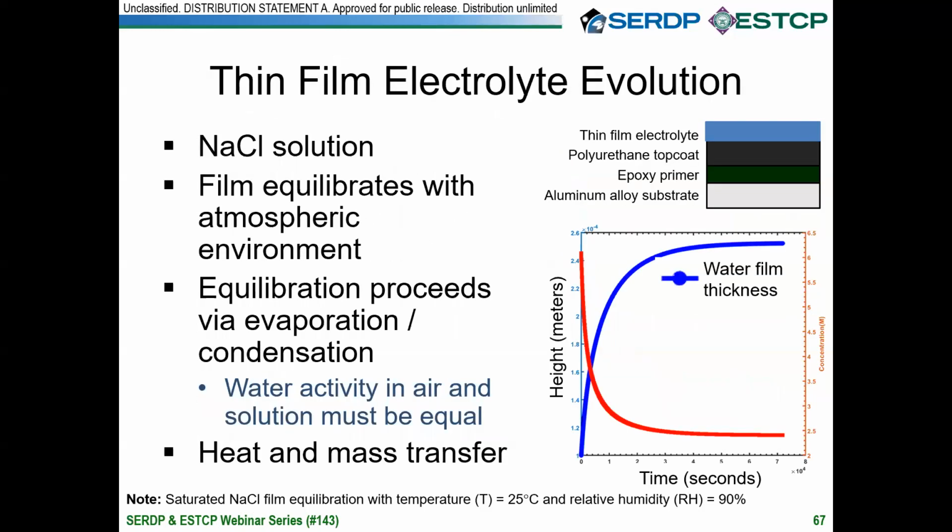So in that previous slide, that's our first physics/regression model for coating degradation. We know that one way to improve that model is to account for the electrolyte on the surface of the coating. And Christine kind of mentioned this in her presentation as well. The water layer that forms on the surface will change in response to environmental changes, such as temperature and relative humidity, because we know that water layer is going to try to equilibrate with the environment. For example, if the electrolyte forms from salt crystals that have been deposited on the coating surface, as the temperature and relative humidity pass through the deliquescence point for the salt, water will condense on the surface and form that electrolyte, but it will be in a very nearly saturated concentration.